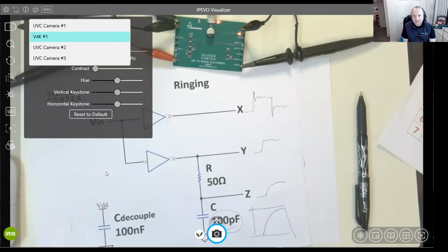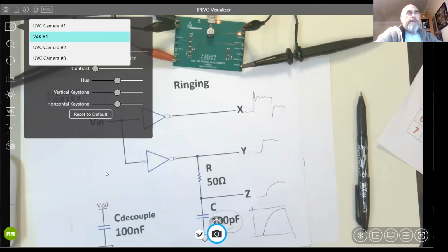But yeah, the PCB layout will be absolutely everything. If you're turning things on and off, you can definitely expect to have power glitches. When you've got capacitors on board, they're going to want to charge up, so you're probably going to be in for a rocky ride, believe it or not. At least everything will happen very slowly at the application level. I could afford to not take any samples for a second or 10 seconds after.